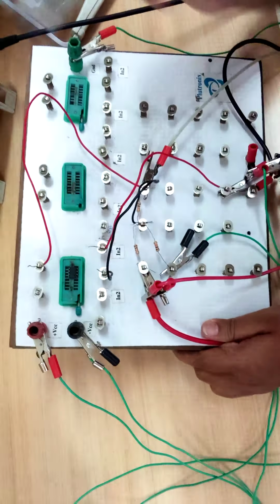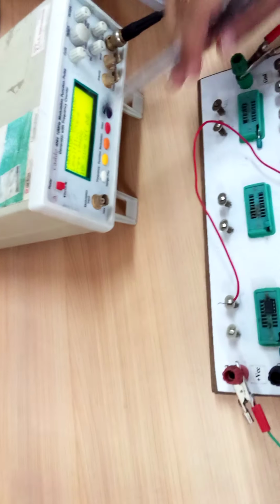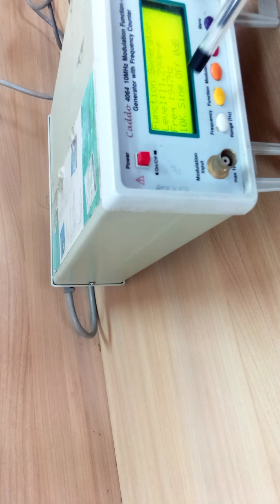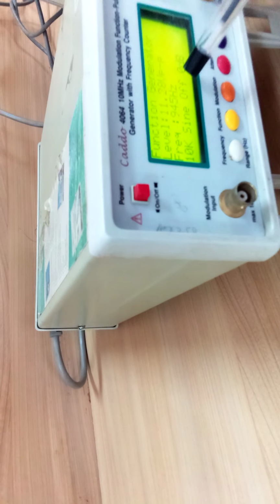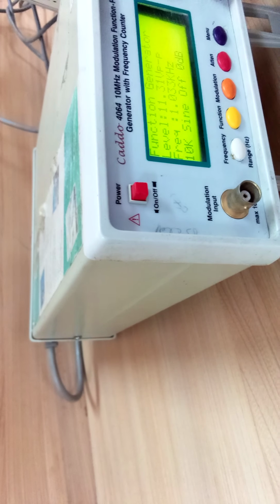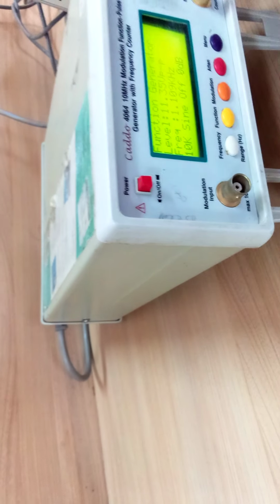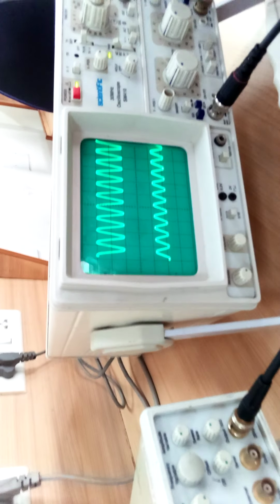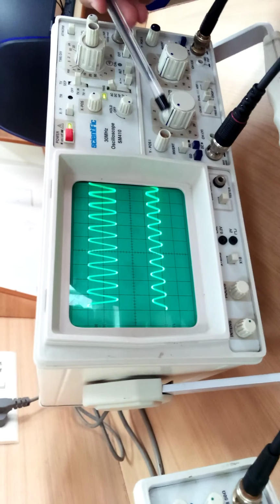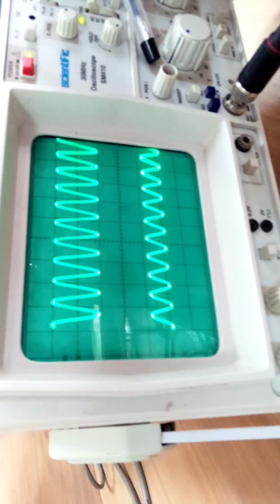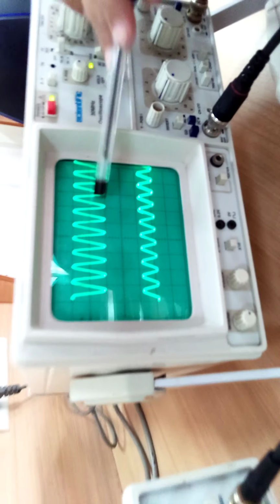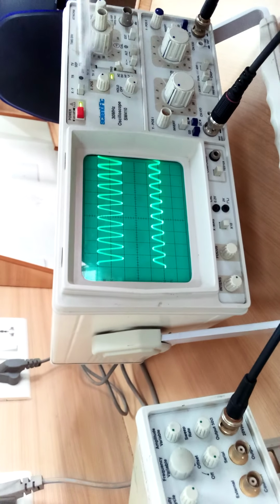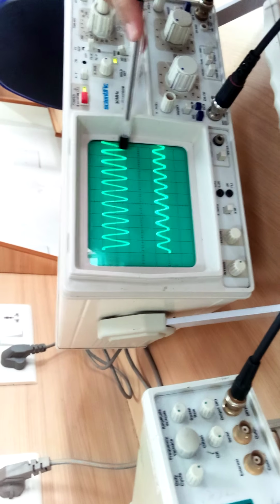You can observe here I have connected the AC input. So I have provided approximately 1 kilohertz frequency here. The input frequency is 1 kilohertz. You can set this to 1 kilohertz. Then amplitude is 2 volts peak to peak. See, this is the input signal. Input I have provided a sine wave. So the volt per division knob is pointing at 1 volt. So 1 into 2 divisions which becomes 2 volts. So 2 volt peak to peak input I have applied.